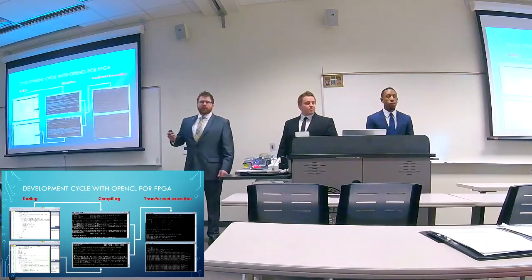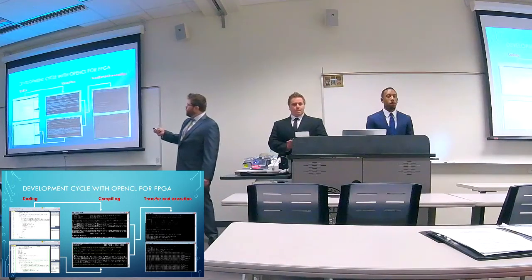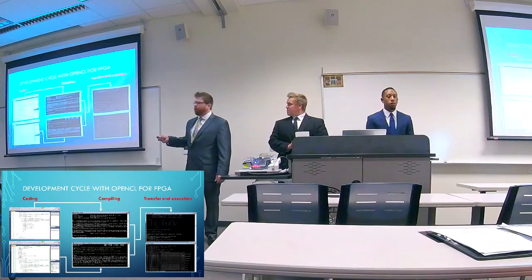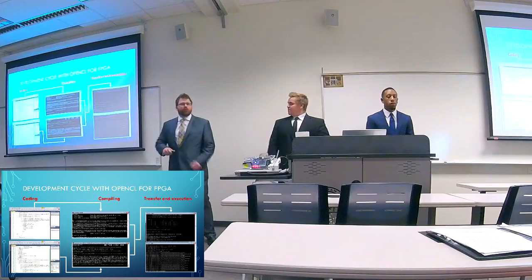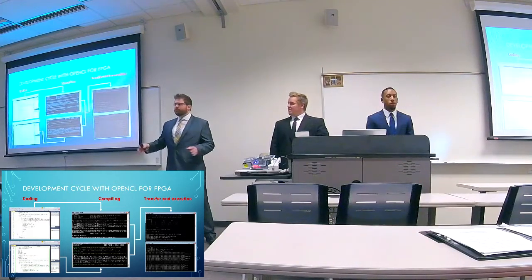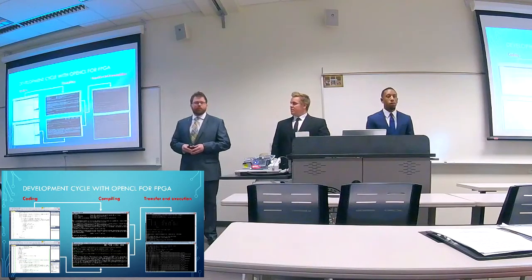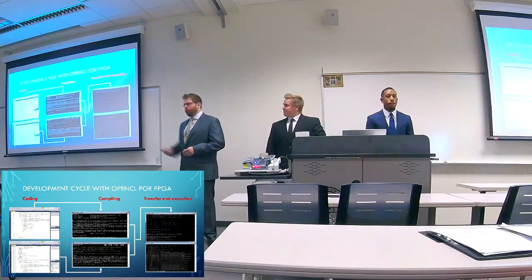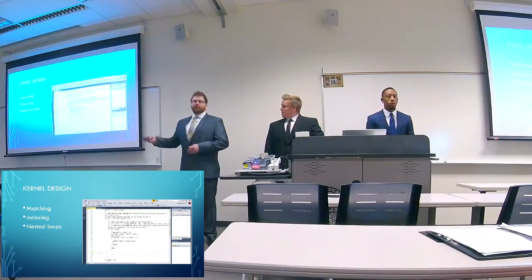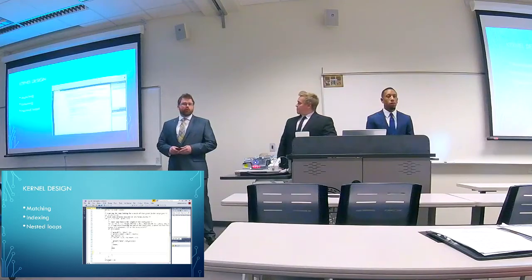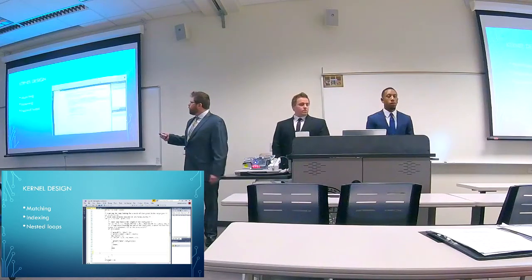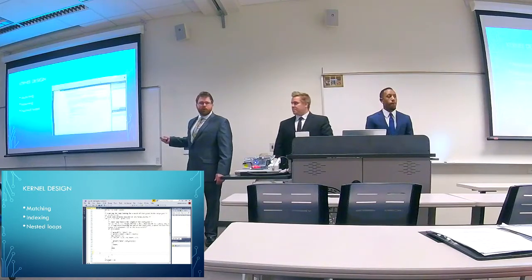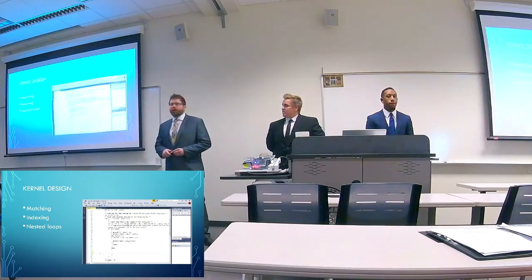So when we started the project out, we had to do coding two different ways. We had to do it on the kernel and on the host. Then we had to compile it on both, transfer, and execute on the FPGA. A little cumbersome, and we did develop a tool set to help make that a little simpler. We'll go over that in a moment. This is an illustration of the screenshot of the kernel design. So basically what we're showing here is we are writing this in C, and we are also doing nested loops here to help with our indexing and optimize our spatial locality.